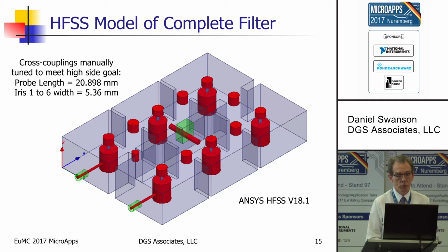And these little blue rectangles are extra ports that I've added into the model so that I can port tune this model. So instead of analyzing a 2-port here, we're actually analyzing an 8-port circuit. And when we bring it into the circuit simulator, we can use very fast circuit theory simulation to modify our project.